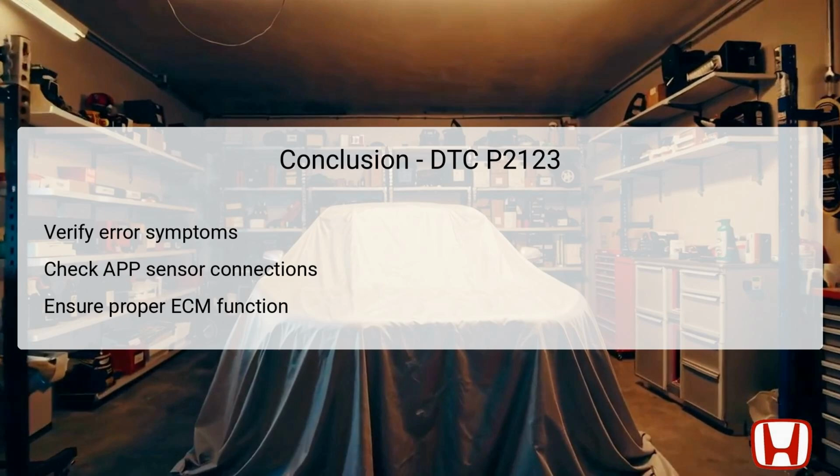The first troubleshooting step focuses on checking voltage readings and connections. If necessary, replace faulty components and verify proper wiring to ensure accurate signals to the ECM. Lastly, follow the final repair verification steps to confirm the successful resolution of the DTC.